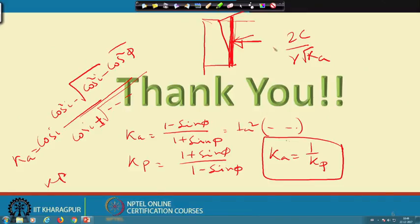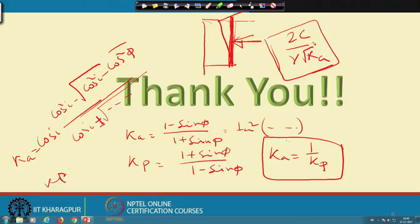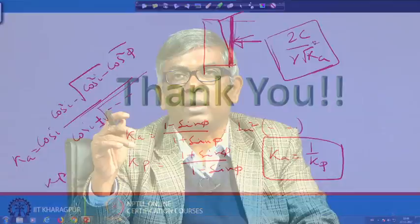Do not get confused. If it is asked for the depth of tension crack, the crack will extend up to this point, where pressure is 0. Beyond that the pressure is positive, so a tension crack will not be there. If the depth of tension crack is asked, then this is the answer, and if it is asked for the maximum depth of unsupported excavation, then it will be twice of that.